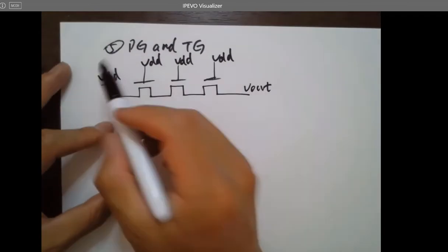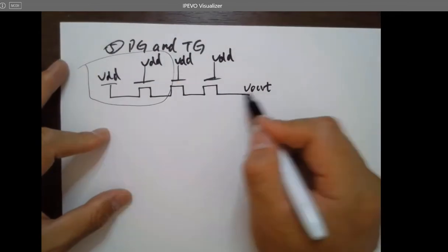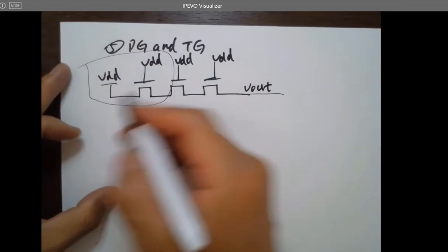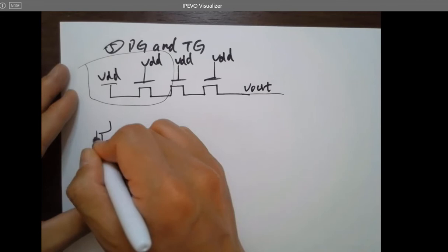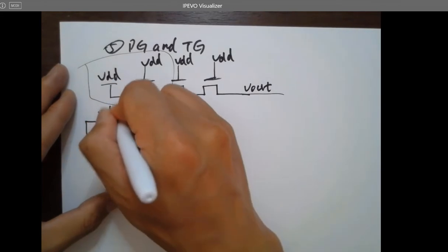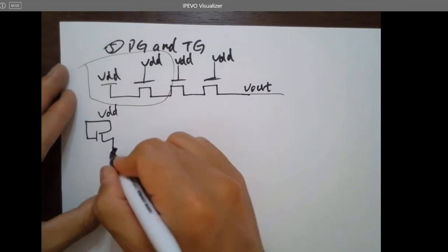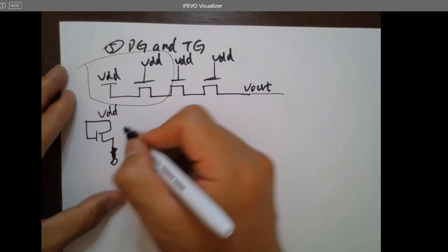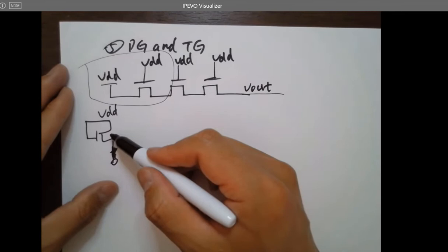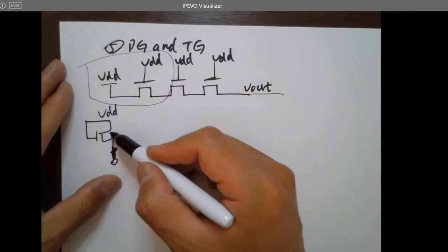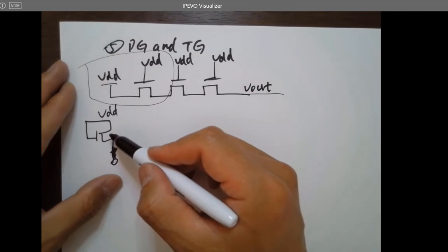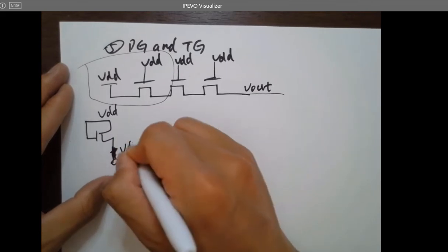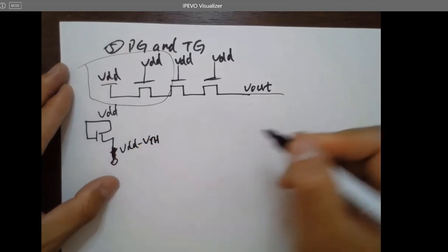All right, so just look at this part first. The question is, what is VL for this circuit, right? Just look at this part first. This is kind of similar to this. It's not similar, it's exactly the same as this, right? Remember, we don't ground it, just a terminal. So for this circuit, this NMOS is being self-biased. It is always turned on and always operating in the saturation region. So when you are trying to pass VDD to here, you're only getting VDD minus VTH as a maximum.